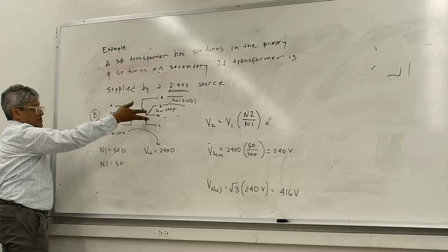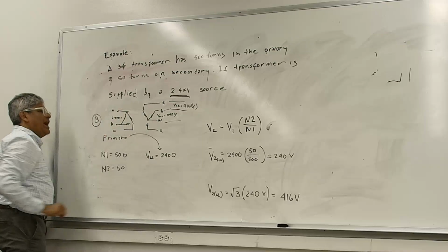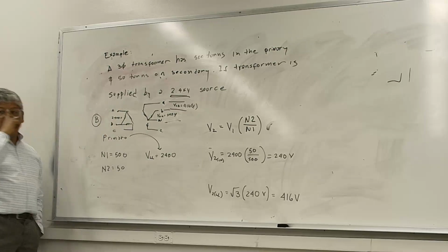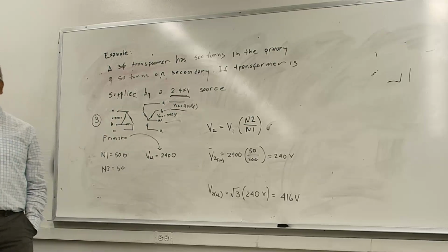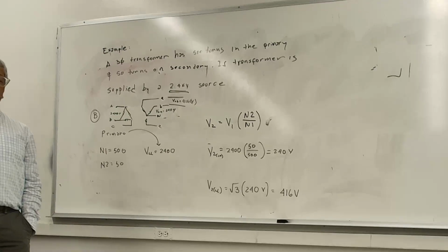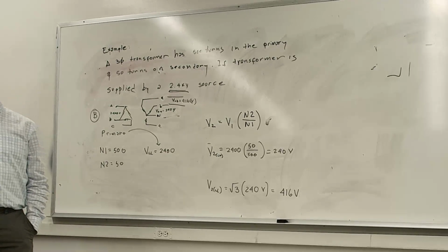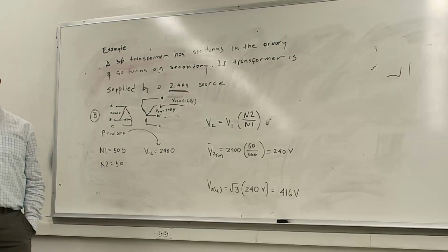First, they have to tell you how they're connected, and then they have to tell you the voltage. And when they give you three-phase voltages, if anybody tells you this is a three-phase voltage and it's 12 kilovolts, 16 kilovolts, 4 kilovolts, it is always, they don't have to tell you, line-to-line voltage. Whether delta or Y.